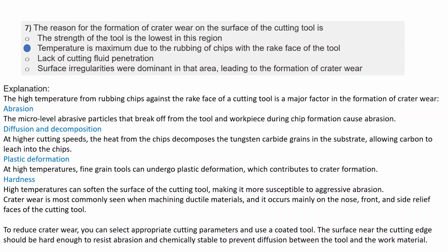To reduce crater wear, you can select appropriate cutting parameters and use a coated tool. The surface near the cutting edge should be hard enough to resist abrasion and chemically stable to prevent diffusion between the tool and the work material.